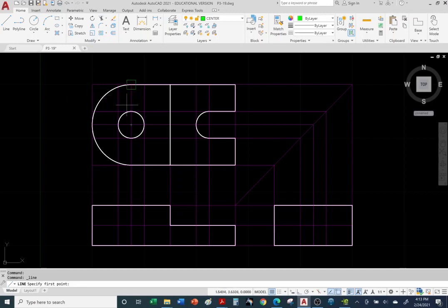Okay, so I'm gonna aim towards the center, so I'm just hovering over the center. And notice it's recognizing the center of the circle, and then I slowly pull away horizontally and it's tracking. See how you see that little tiny white X? That lets me know it's tracking that center and it's staying horizontal as it's tracking. Let's go back. You have to pull away slowly for it to work. If you go too fast, it will not track.